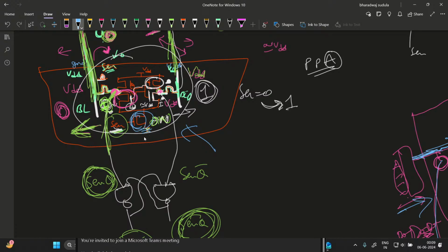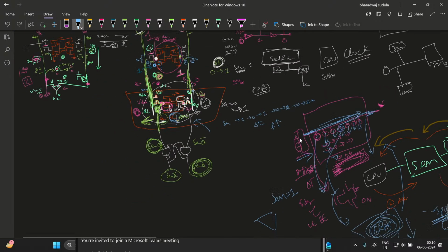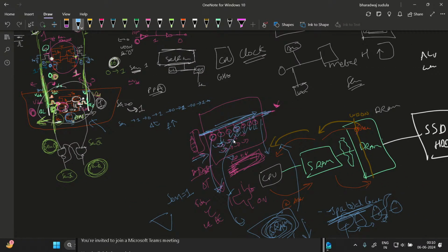There should be no ground connection. So you need to enable this sense amp again and again. It will turn off, on, again and again, for a very small period of time. This is where you have this high frequency of memory access. This column switching is really fast, and for that you need really fast sense enabling timing, like a clock pulse. That is where self timing comes into the picture.